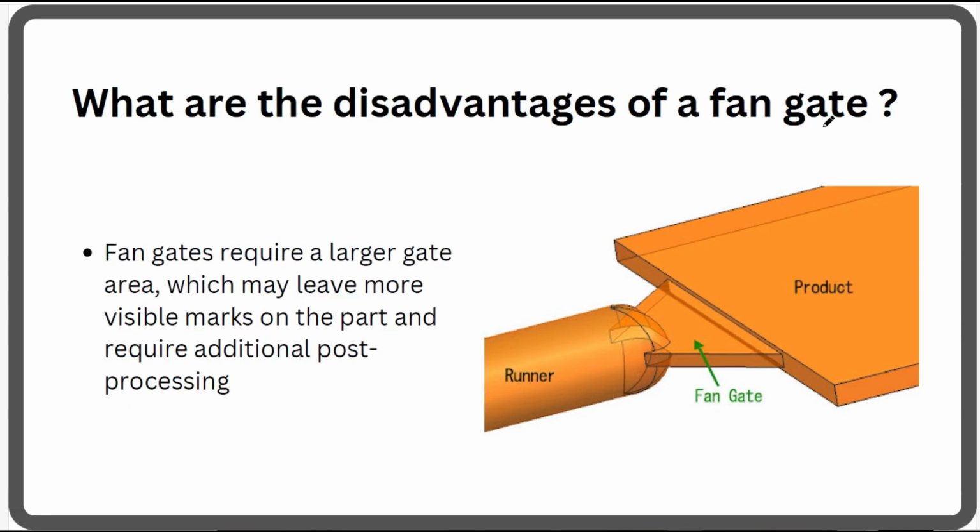So what are the disadvantages of the fan gate? You can see it covers most of the larger area, so it leaves a larger visible trimming mark. After cutting this type of gate, a visible mark will be left on the final product.